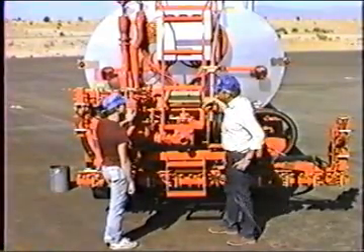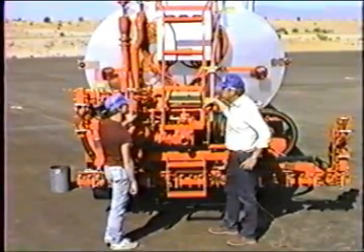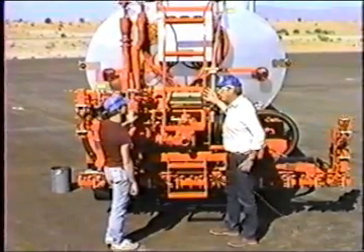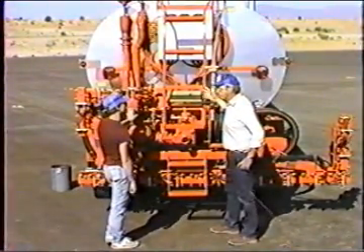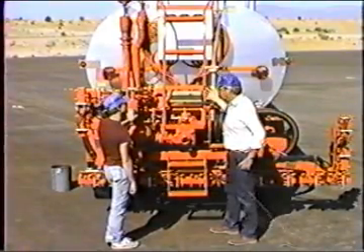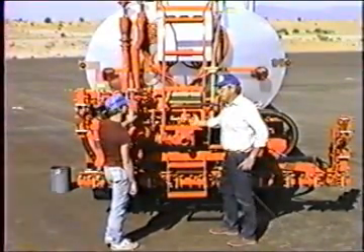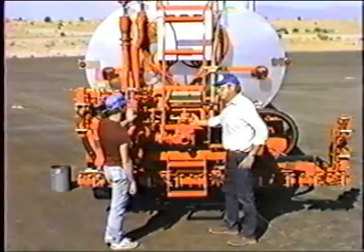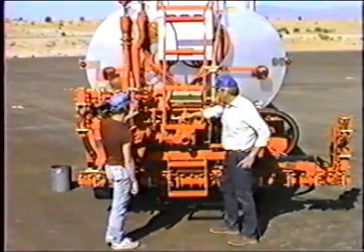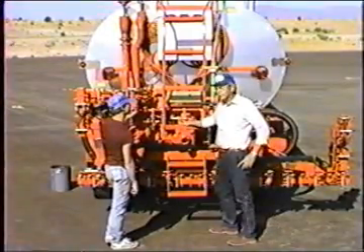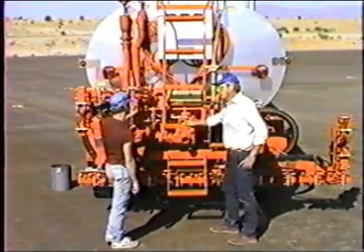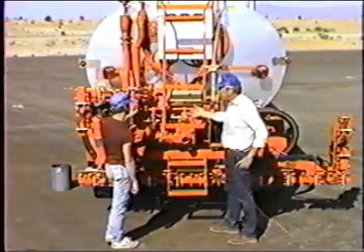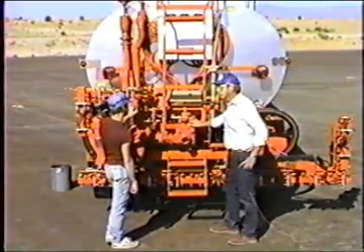Since this is a brand new machine and next week's going to be your first week out with it, after the second or third day, at the end of that shift, stop and clean it. When you're all done, take them apart and clean them. If there's nothing in the screens, that's going to tell you that you could have waited maybe 2 weeks the next time. If the screens are half full, that means that maybe you're going to have to clean every day. And you just have to learn from experience and know what kind of materials you're getting and when to clean.